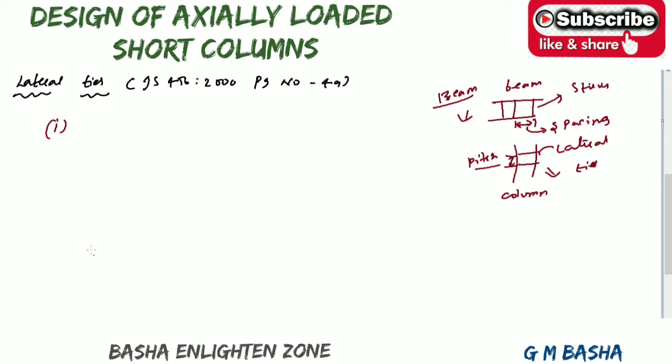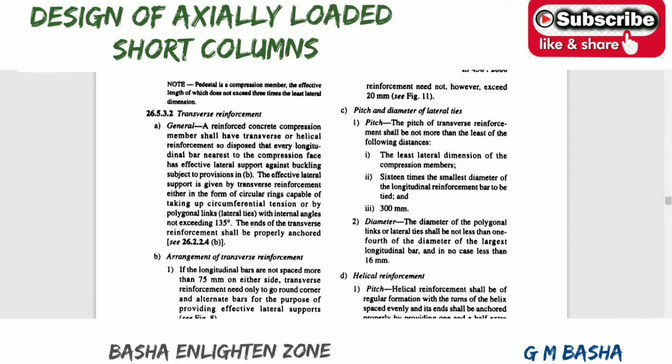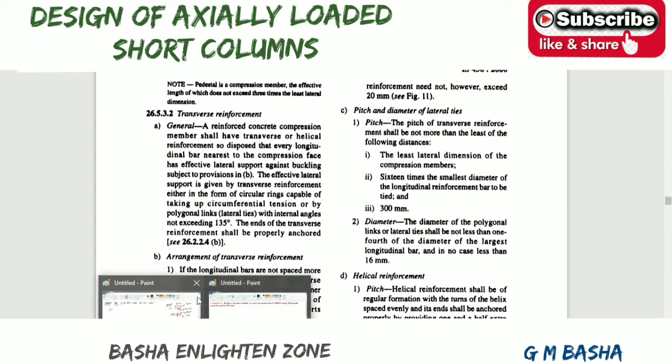Then the diameter of the lateral ties according to the code shall not be less than 1/4 of the diameter of the largest longitudinal bar, and in no case less than 6 mm. So it is not 16 mm. Please correct this value, which is 6 mm. Why? Because the minimum bar used for lateral ties and stirrups will be 6 only, not 16. Please make that correct.